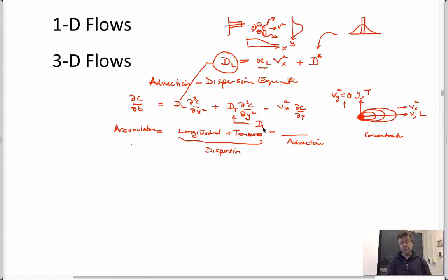So the longitudinal component would be equal to, sorry, wrong, right? The transverse component would be equal to a coefficient that represents this behavior, but the advective velocity in the x direction, just like this one. It has to be the advective velocity in the x direction, not the y direction, because it's 0. And we want to index it here with some mechanism that's causing the spreading. We'd add to this also this diffusion effect on it. So that in a physical sense is what's going on.